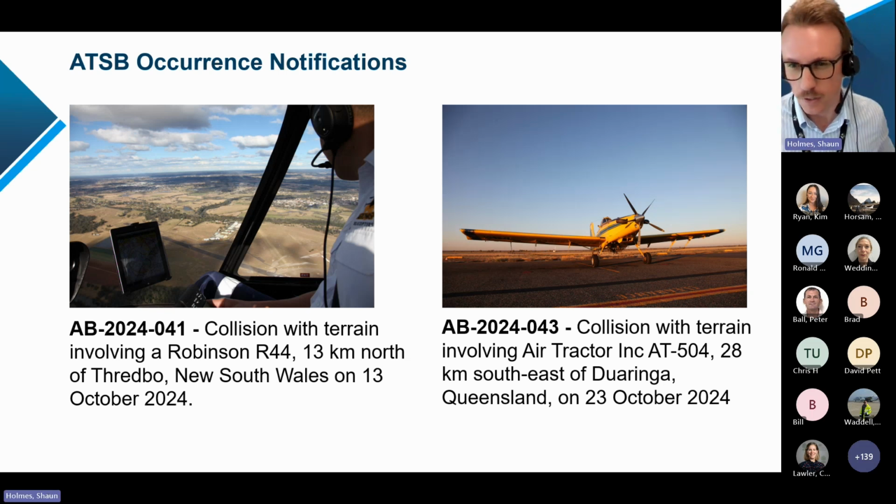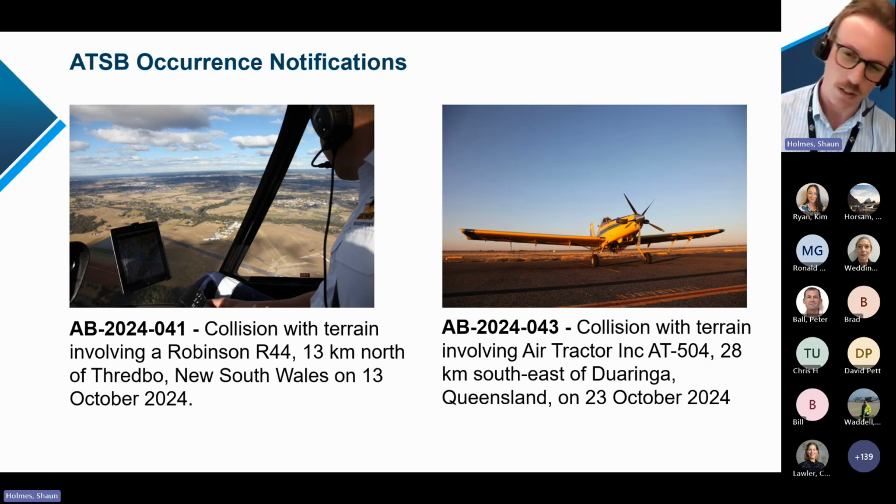During the climb, after retracting the flaps, the aircraft suddenly yawed sharply to the left. The pilot reported being unable to control the aircraft effectively and, my apologies, reduced the power to bring the aircraft back to a more level state.